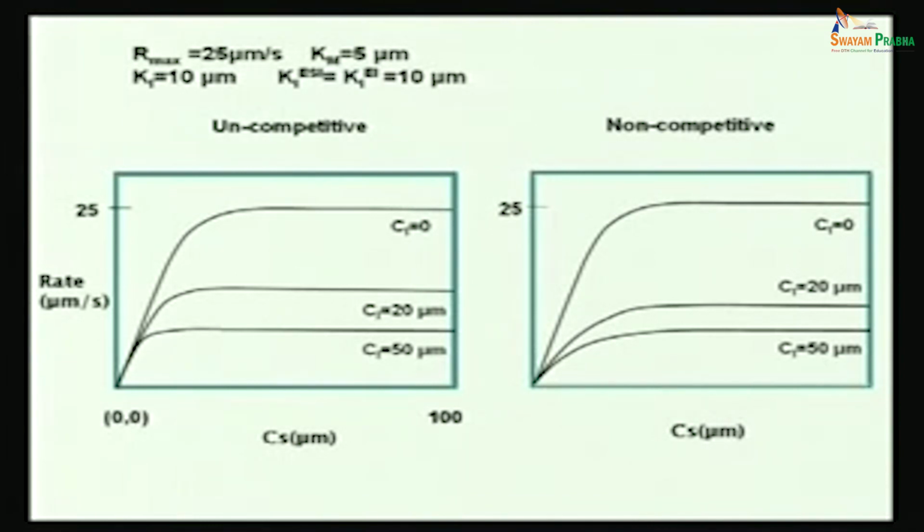What would be large in a large CSTR? Yeah, volume large means what? The residence time, right? The residence time is large in a large CSTR, right? So if the residence time is large, and even if you are taking the product out at a certain rate, still, because what does residence time signify? It signifies the amount of time, not the exact amount, but a representative amount of time that each of the species gets to spend in the reactor, right? That is the definition of residence time.